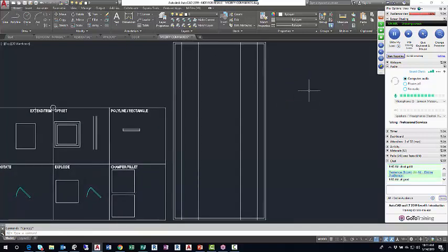I've got 4 new lines that were created using the offset command, but I had to use the explode command first. So these commands sometimes will go hand in hand if you're using polylines. I wanted to use a polyline or a rectangle to create the outer face of the floor plan, so when I use the offset command, all 4 sides came in at the same time, and I didn't have to trim the corners up to make things neat.